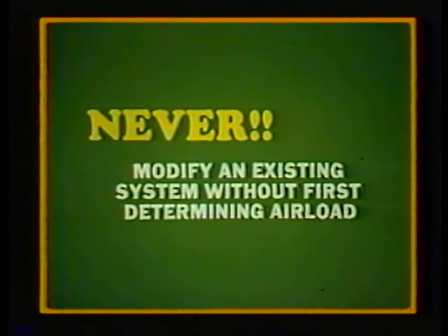Never add equipment unless approved by the airframe or pump manufacturer for a particular installation. And do not modify any system without first determining if the total air load is within the operational capability of the pump.